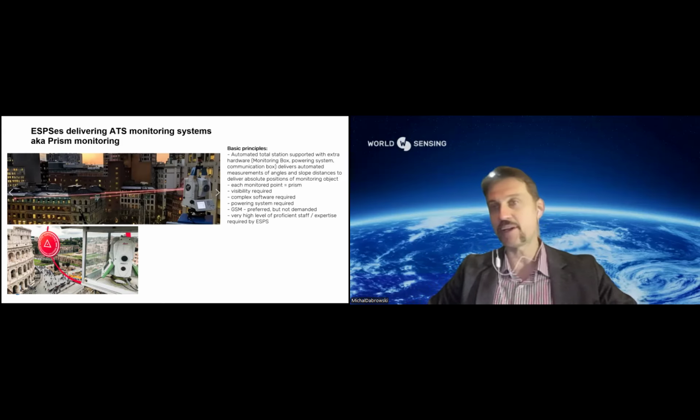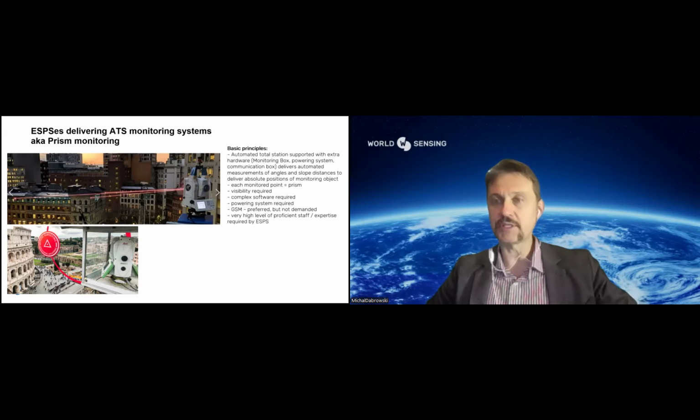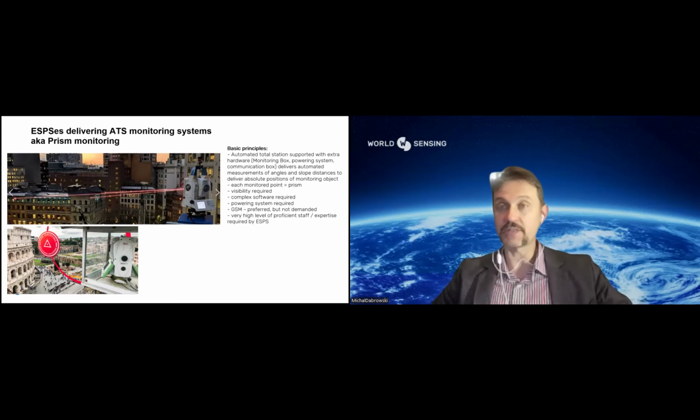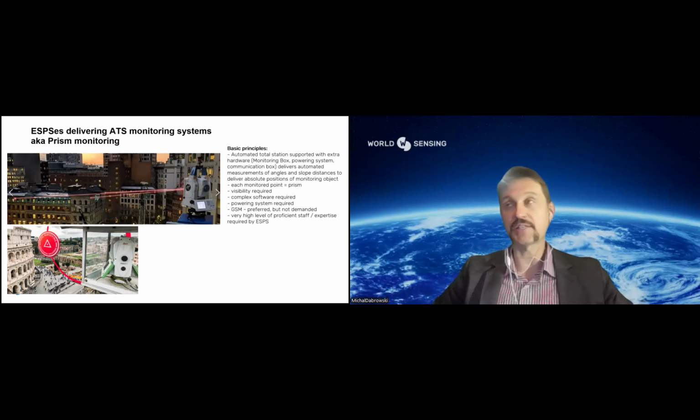Whether you have night, day, clear sky, fog, or rain, GNSS will perform equally. There is no optical need for visibility between base and rover, which needs to be present for your prism monitoring as well as for your radar monitoring.